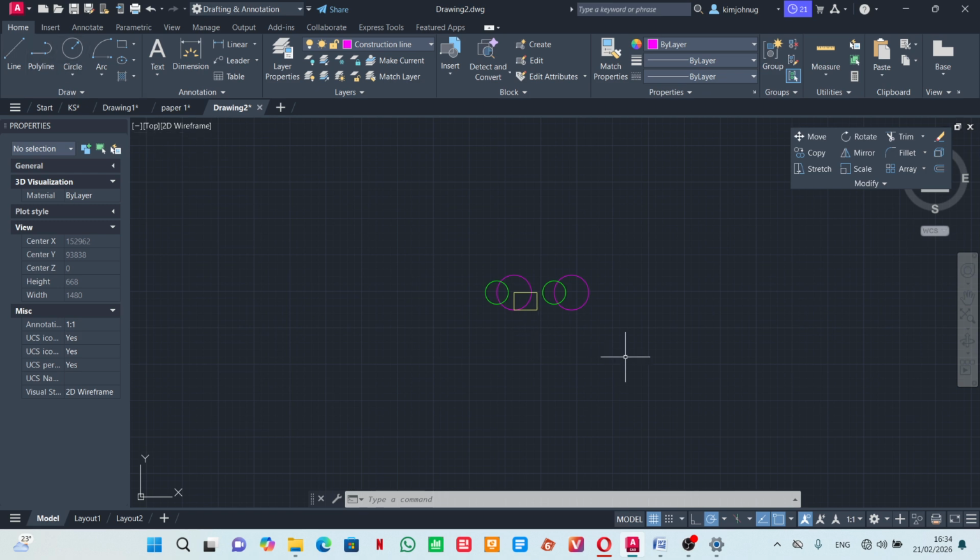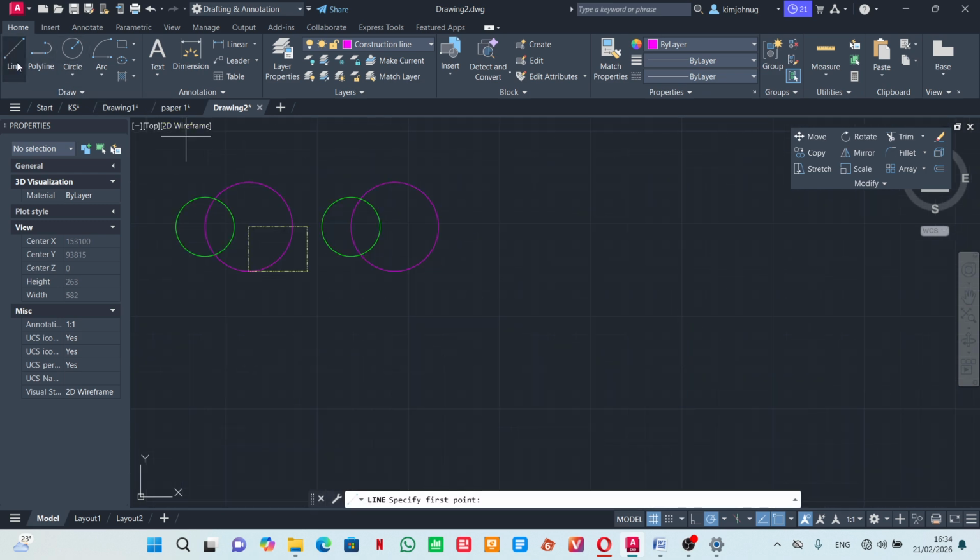If I'm trying to draw a line, these lines will be in intervals of 5s. If I select 30, this line will be in intervals of 30, 60, 90. I prefer it in 15. No major reason, just like the 30s. That's the ortho mode.